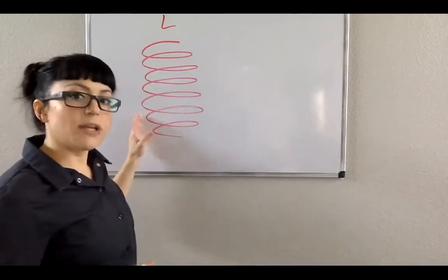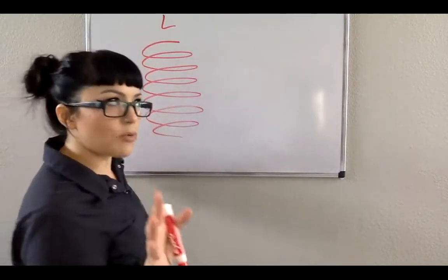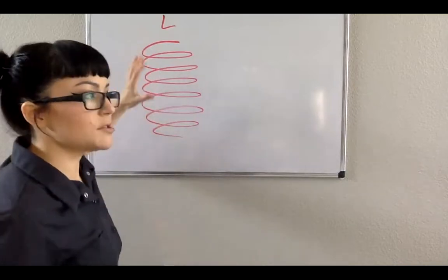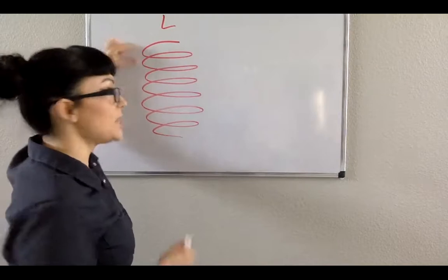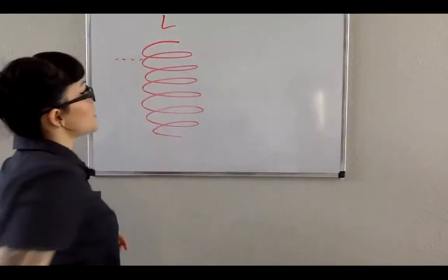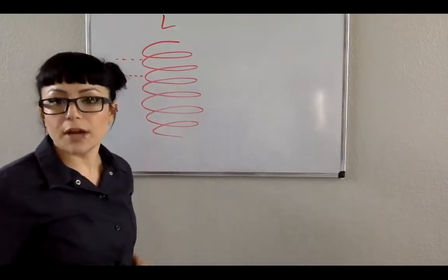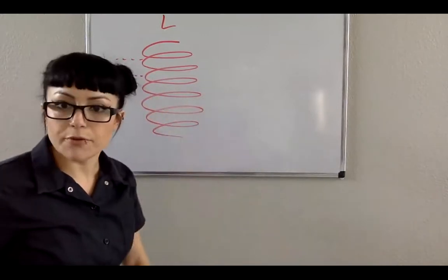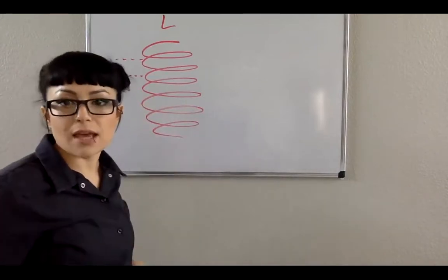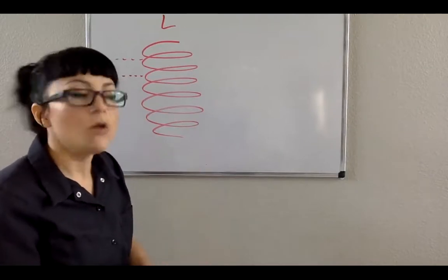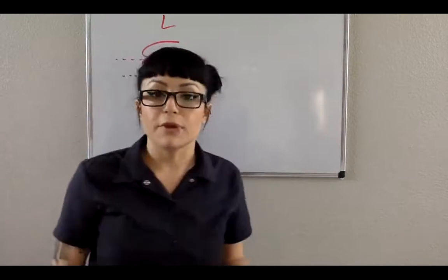A linear rate spring is going to be the same no matter how much you compress it. And I won't get into too much detail here, just some basic theory. If I compress this spring 1 inch, I'm not measuring it, but we'll say 1 inch, that takes 100 pounds. If I want to compress it another inch, I'm going to have to add another 100 pounds, and so on and so forth. If I added 300 pounds, it will compress the spring 3 inches.